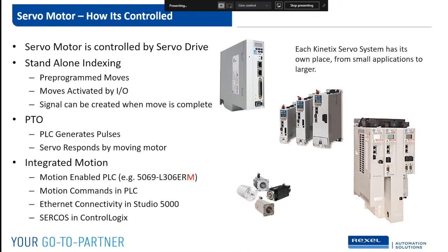They can also run on the PTO output, just like the steppers do that Rob just talked about, and take that step direction input. So say you have an application where a stepper doesn't have the speed you need, but you would like to use, like, an 850 servo or 850 MicroLogix. You could take and use that PTO output and run it into the standalone drive and get the higher torque and higher speeds you need without buying a more expensive front end.